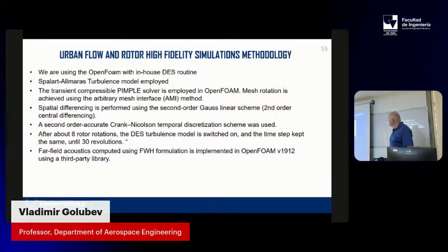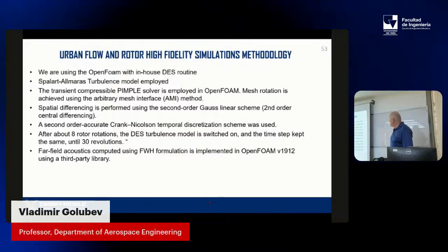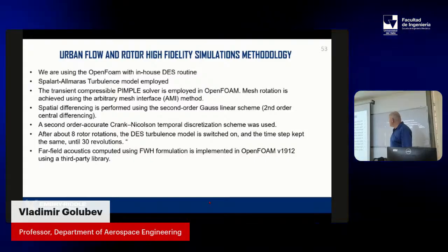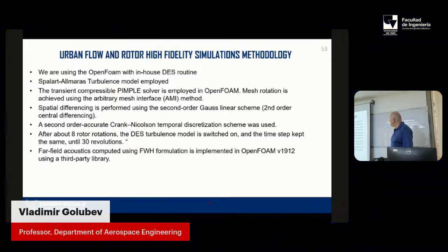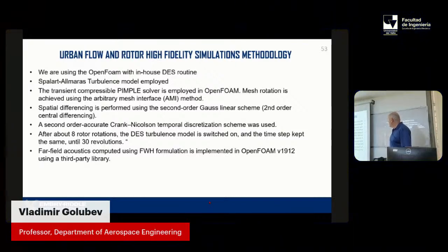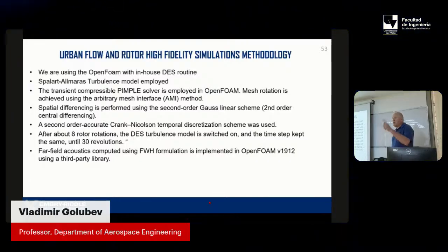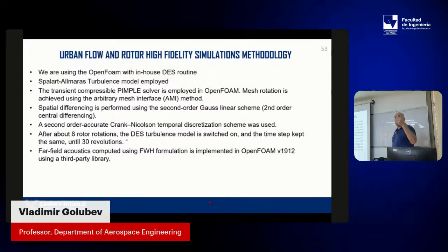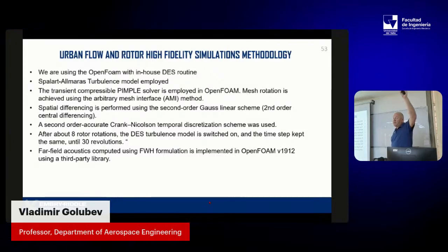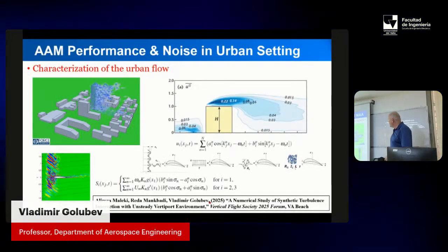That was done using OpenFOAM. We used OpenFOAM for DES, detached eddy simulation, with a pressure-based solver, using second order Gauss schemes and second order accurate Crank-Nicolson for time, over 8 rotations. Usually you accumulate a time sample of 8 rotations, and then you check the acoustics in the near field, and you propagate to the far field to predict the acoustics. Usually that's the process. It requires a lot of things.